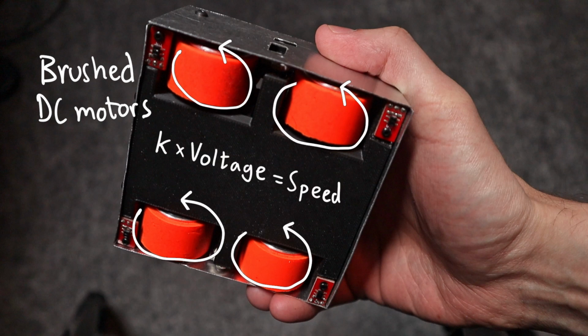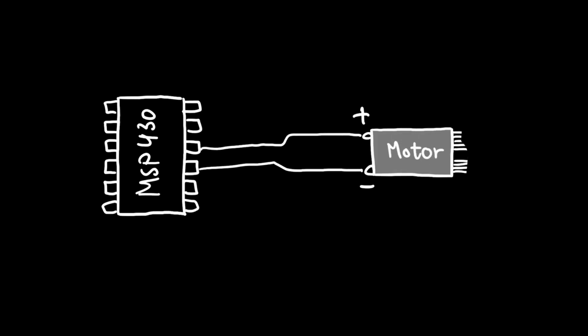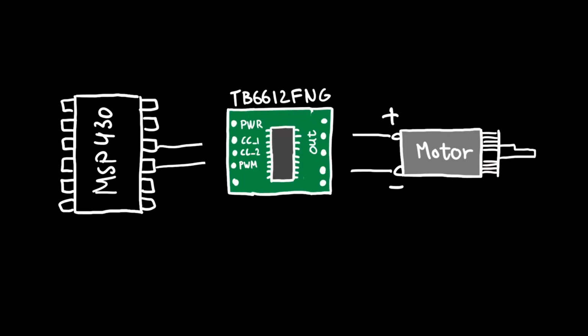The speed and torque are proportional to the applied voltage, so you vary the speed and torque by varying the voltage. But the motors can't be directly connected to the pins on a microcontroller because they draw quite a bit of current, more than a GPIO pin can supply, so you need a motor driver.